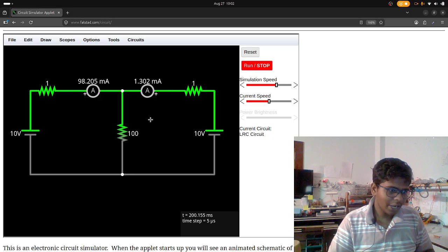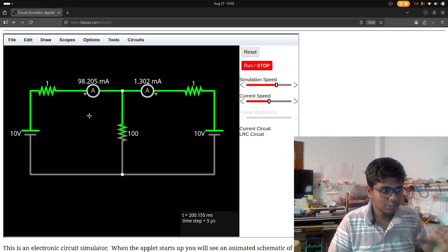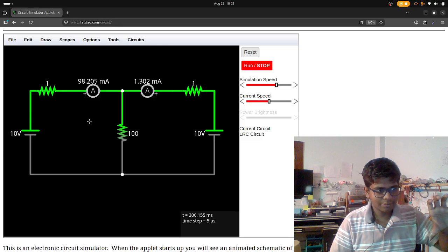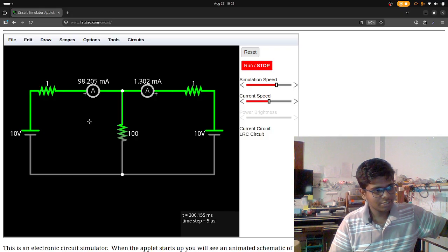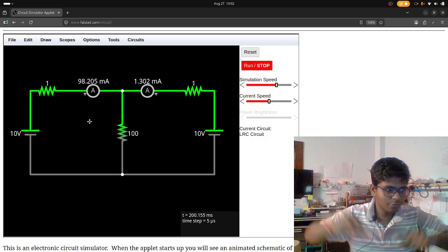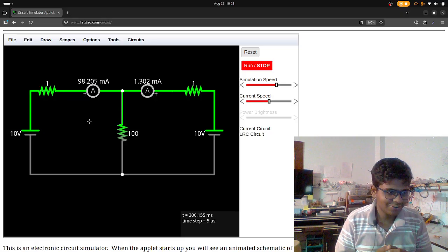And here we considered ideal conditions, for example the same resistance of the transmission line on both sides, which is physically nearly impossible, because suppose generator one is at a distance of 10 kilometers from the load, and my other source is at a 20 kilometer distance, then the resistance will also vary, which may lead to several other problems. So think about it a little bit: is DC synchronization easy or not? Thank you.